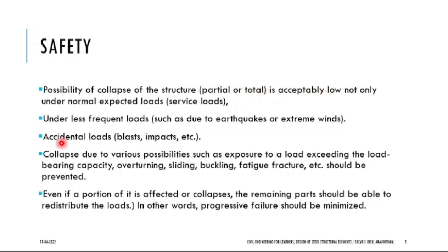The next thing is frequent loads such as earthquake and extreme winds. So when you are designing for safety, you should always check the two forces, earthquake and wind. You should check these two concepts when you are designing for safety. And also there might be accidental loads. It might be due to blast or it might be due to impact.